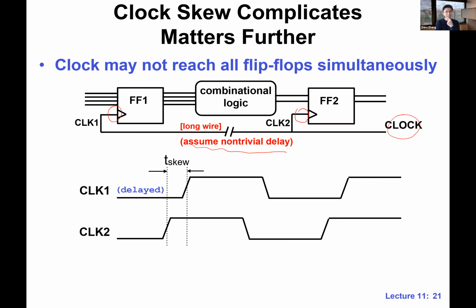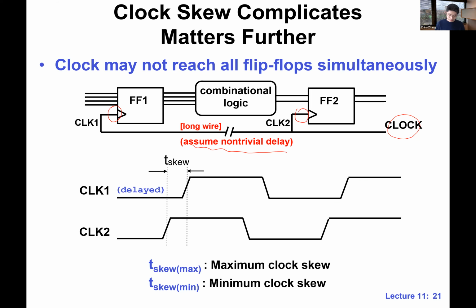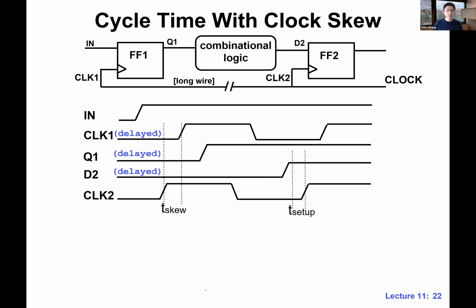Okay. All right. So this is that, right? What does this mean? Intuitively, this means that effectively, because of the clock skew, the clock period gets narrowed somehow, right? This is the analogy. This is the intuition. But let's try to analyze this. First, we also have min and max. We usually have this different depending on the condition of the circuit. You may have a maximum worst case, or minimum case, or a maximum case, right? So let's look at how we actually solve this setup time constraint when the clock skew is in the picture.